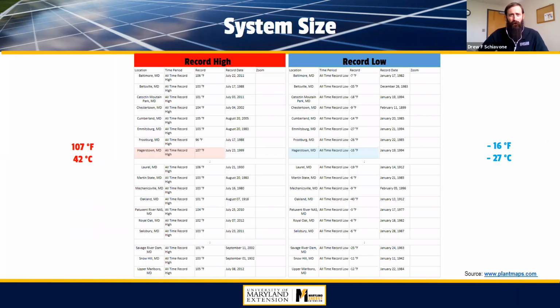Now, I know we're running low on time, but I just want to touch on some of the inverter aspects as well. When you go to select an inverter, remember, it's receiving the direct current that comes out of the panels, out of the modules. And how you size an inverter to work with those panels is based on the voltage. Typically when you look at an inverter, it's specified to work within a voltage range, from a low end of the voltage up to a high range of the voltage. You want to make sure that you don't send too high of a voltage into the inverter, or it'll fail.